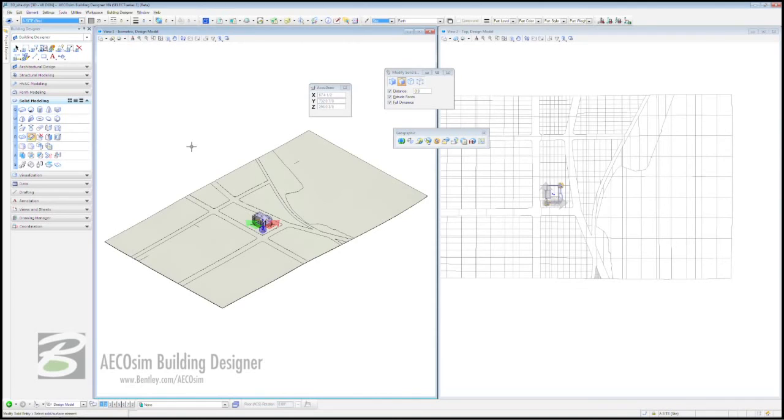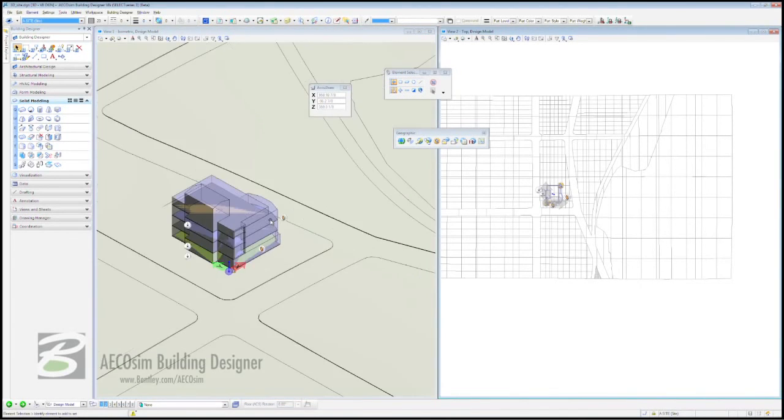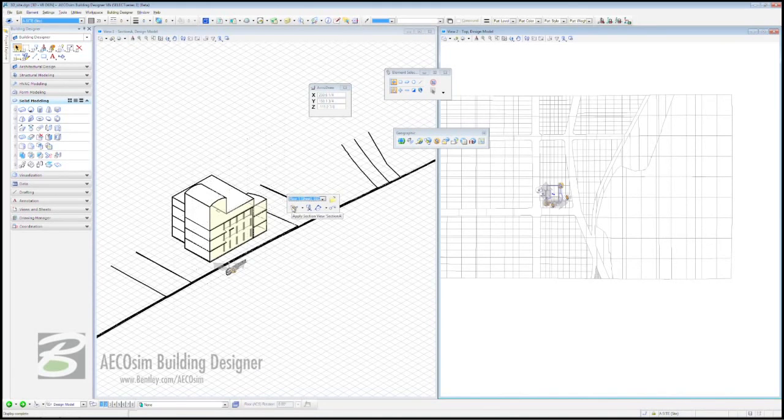And there we have it. All the roads of our site have now been elevated, all the areas bounding them have been elevated by almost a curb height of 8 inches. And now if we zoom back into our structure, you can see that we still have those markers that show us where the cutting planes of our original sections are. So let's go and impose one of those sections, and this will help us coordinate, bringing together both our emerging 3D terrain model and our georeference file.